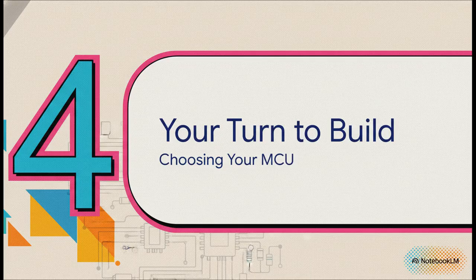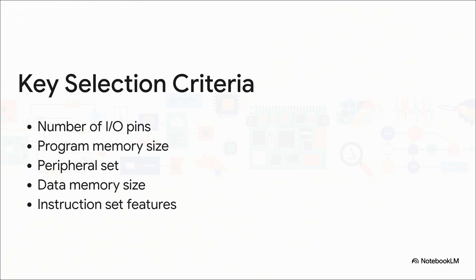Now, that refrigeration unit is just one example. The core skills, making a blueprint and budgeting your I/O, can be used for pretty much any electronic project you can dream up. So how do you actually choose one? Well, manufacturers offer a massive range of microcontrollers, from tiny little 6-pin chips to absolute 80-pin beasts. Your choice really just comes down to matching the chip's features to what your project needs. Do you have enough I/O pins? Enough memory? Does it have the right built-in tools, like an analog-to-digital converter or timers? Your block diagram and I/O budget will give you all those answers.